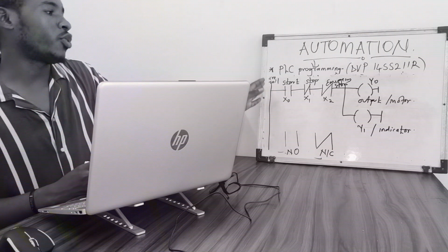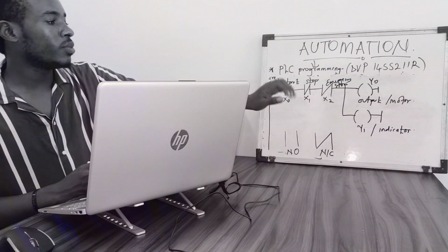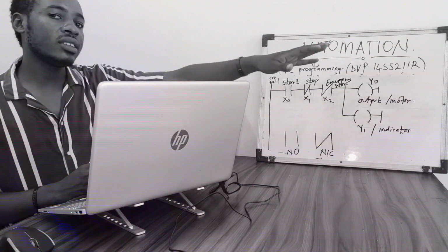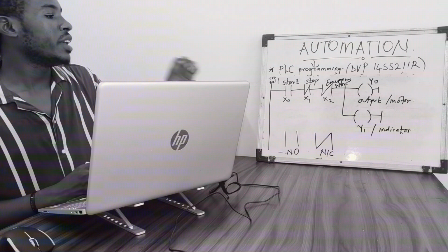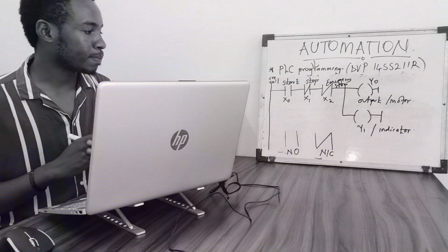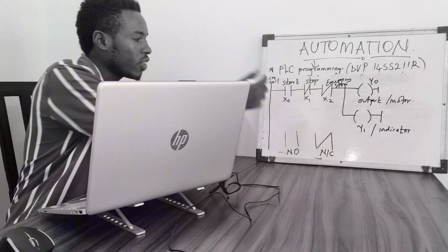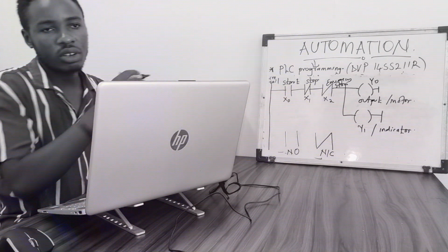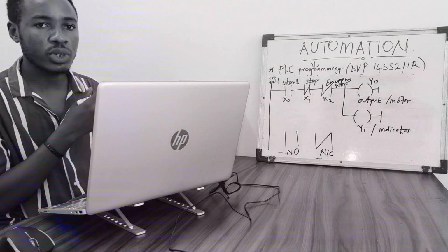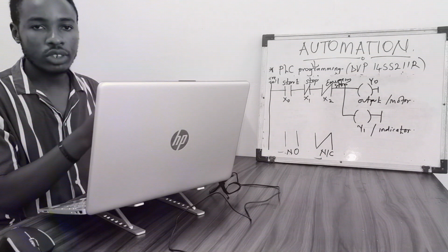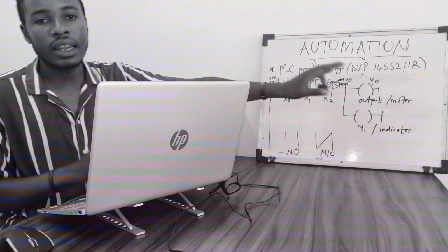It's from this side to this side, and from this side to this side. Then this is the positive rail, and going to the other end, the negative rail. Then you have to understand that we have different types of elements you're seeing there. This kind of element is something I use to represent a switch, like a contact, and then this other side represents an output.